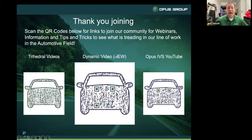But if I am given the option to do static or dynamic on the car, say with the newer Toyota, Lexus, Volkswagen, Audi, I'm going to do the dynamic, right? I don't want to bother setting up the targets and things along those lines. I'm always going to opt for the dynamic, because at that point, you're pretty much putting all the faith in the vehicle to do the calibration. You're not worried about, hey, did I miss this by 5 millimeters of a measurement, with a tape measure, string line looks straight, but it's a little bit crooked, right? Always go for dynamic if you can.